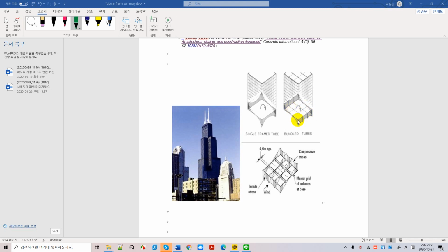If this is the tension phase, your loading can transfer into the columns on the compression phase directly, so that we have a uniform distribution of the load here, and we have a straight line distribution for web frames. And this is a uniform distribution on compression flange frames. And this is a good design, right? This is a very good design.